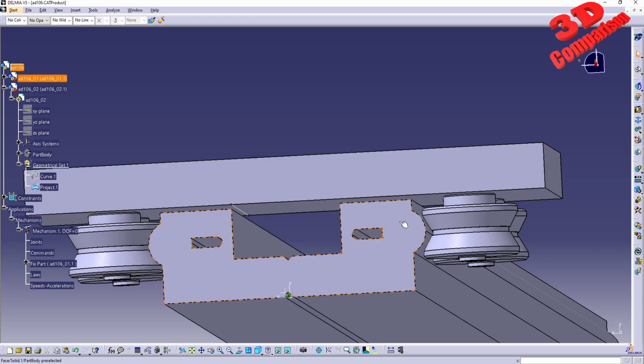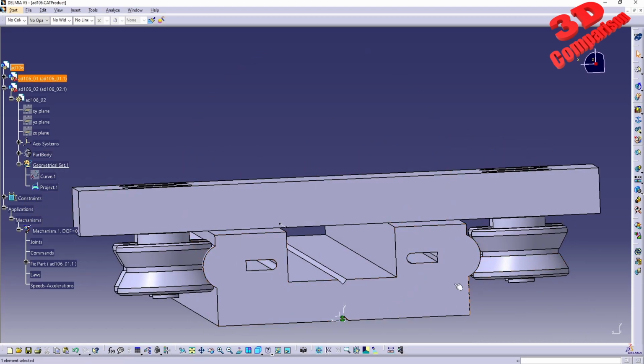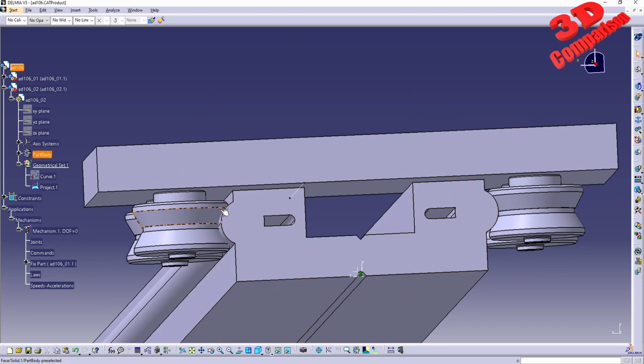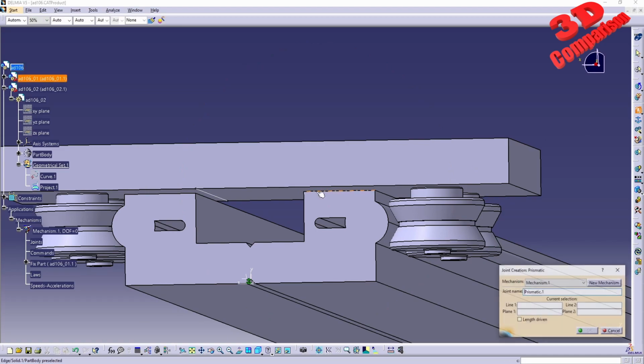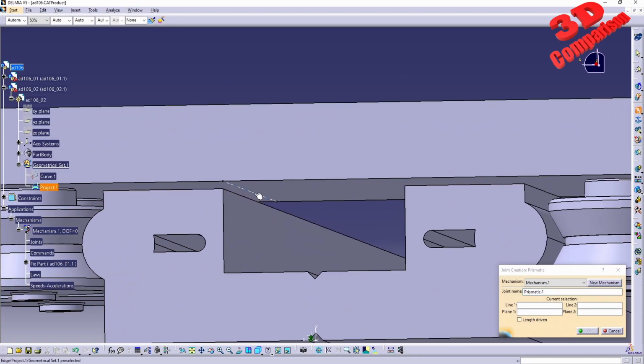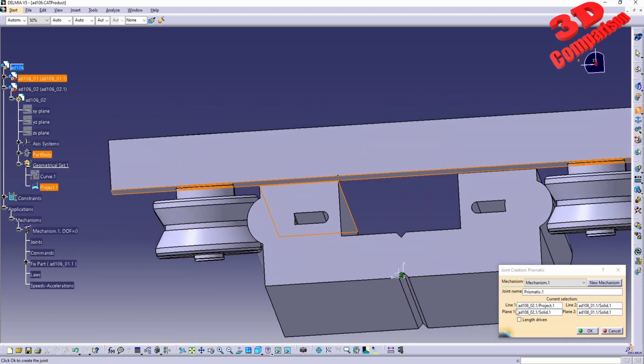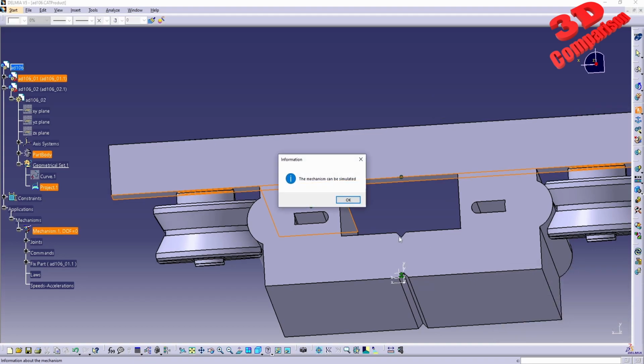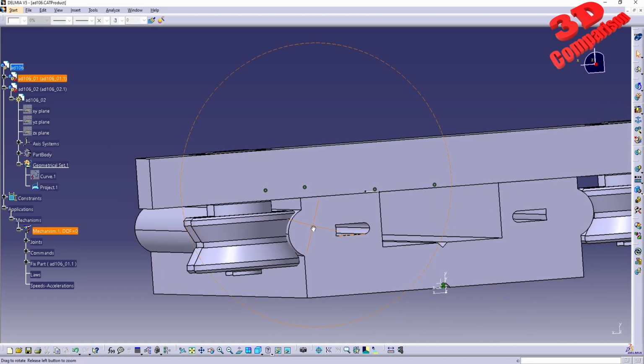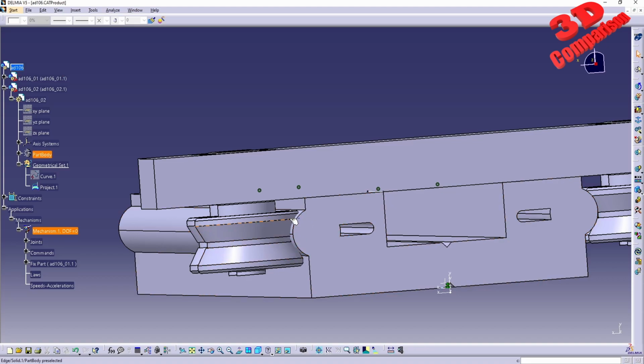The only drawback in this case is that, as we can see, the assembly will have these side rolls over here. So if I will go with a prismatic joint and I want to link the top projected line with the bottom one, we're going to have the two planes where we're going to have that movement, so that top plane and the one over here. If I will make this to be length driven, we're gonna see how the mechanism can now be simulated, but it will no longer respect that offset.